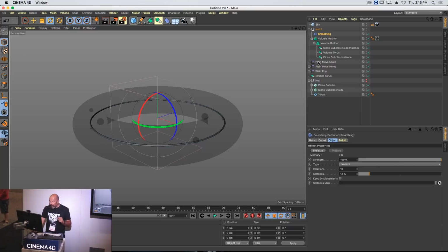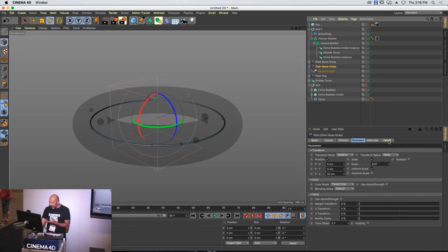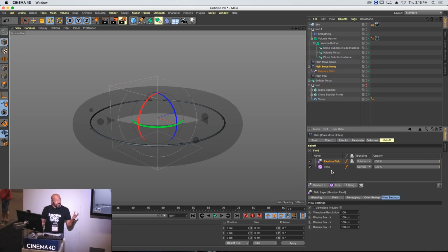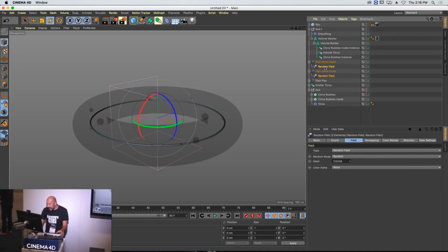Now, setups like this can become even more procedural. In what sense? I've made 3 plane effectors that have the same lists. What I could have done is taking all the common elements, group them under a group field, and use that group field wherever we use exactly the same parameters. And we would be able to save ourselves from selecting this random and changing the values. And because I'm lazy, a click less is a click less. Right? So value is great.